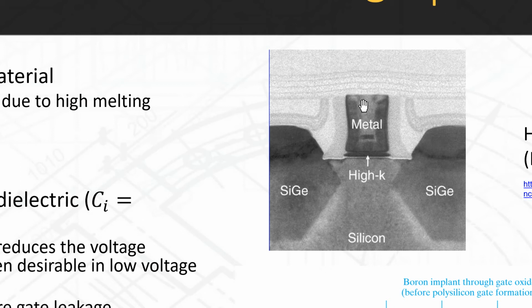The way they do metallization is they alternate depositing insulating layers and metal layers. Each metal layer is patterned. A typical circuit designer would have up to seven different metal layers they can use to route connections between transistors. And the reason they need 7 layers, think about it, if you just had one layer, you could never have metal lines crossing over each other, right? Now, take that problem and multiply it by 1 billion.